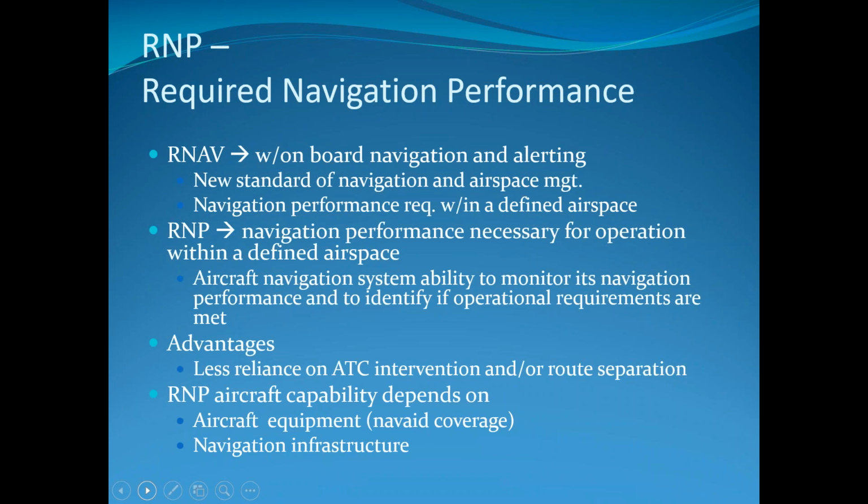If you're flying an RNP approach, and once again, this is a precision approach, it's using satellites, nothing ground-based, but it's using vertical and horizontal guidance. The only thing you have to look at with RNP approaches is the precision requirement, which will be like a 0.1 or a 0.5, and that means 0.1 is 1/10 of a mile, 0.5 is 1/2 of a mile, or whatever it says. Sometimes it'll even say 1.0, meaning precise to within 1 mile. That means whatever signal it's receiving from the satellite has to be precise to within 1 mile of your location.